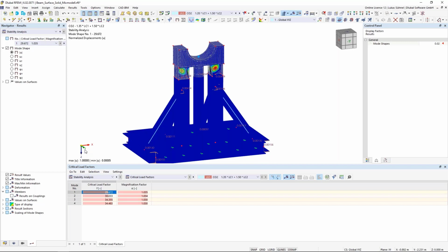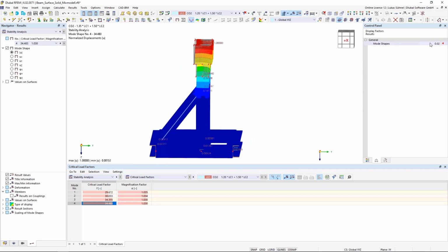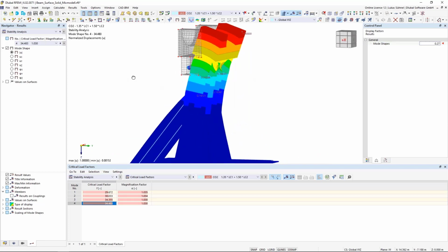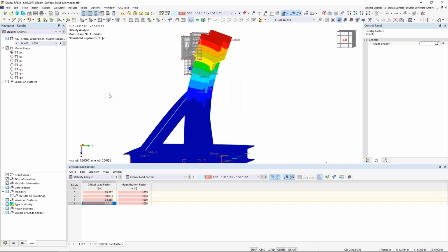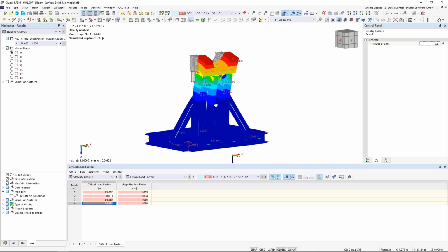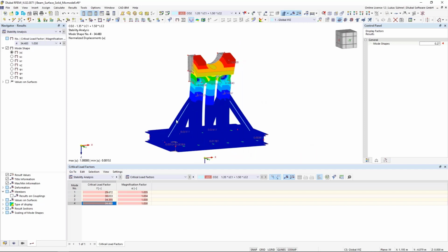If I want to analyze it even further, I would have to look for an eigenmode that actually deals with buckling. This could be, for example, the force eigenvalue eigenmode. And here we see this would be some kind of buckling for my columns. I have here the factor 34.5, so much bigger than 25. So I can easily say buckling is not an issue. Now I excluded buckling and lateral torsional buckling. That means it is enough to simply run a stress analysis for the structure.